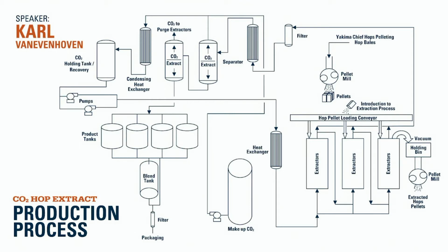Brewers all know what a brew kettle is, and they know boiling. You see the vapor. But let's say you had a really heavy-duty brew kettle, and you've got your level of wort in there, and as you're boiling, that level's going down. If you close that vessel, your pressure would be going up, of course, and then the density of that vapor phase is going to be increasing. And you add more heat because the boiling point's increasing as the pressure is increasing. And then when that level gets down to the very last drop, it's in that supercritical state.